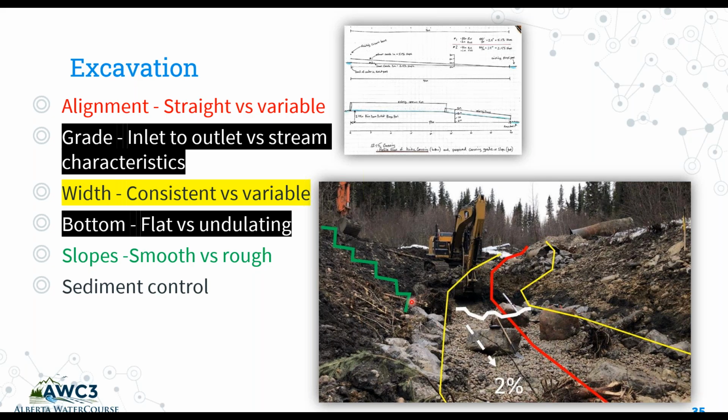Your slopes are going to be different for a creek versus a restoration or a bridge, and you'll want to think about sediment control. Two things I want to highlight: if you're doing a large excavation, try not to overcut your slopes. There's no point in excavating a slope and then filling it back in afterwards. That makes the slopes less stable.